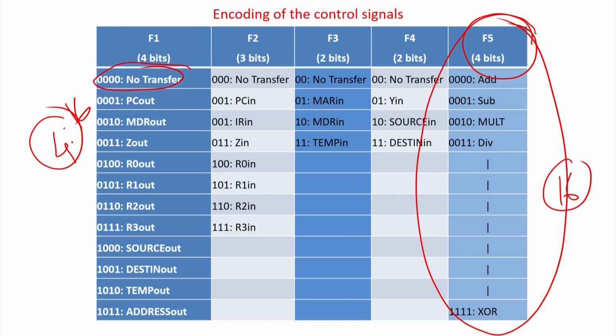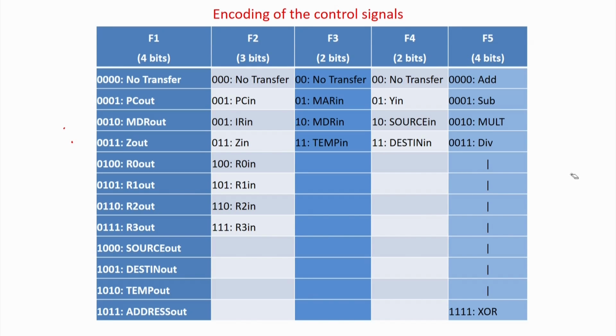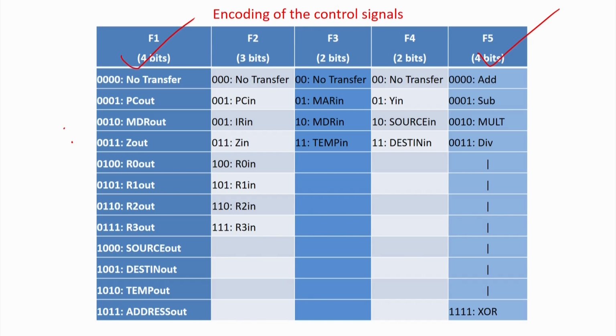If it is a multiple bus architecture, then 2 bits also can be simultaneously 1, and then again you have to break it up in the cluster. So in this discussion we are keeping this thing simple. In a single bus architecture, this is one of the very good ways of doing it. Now the read signals. Read can be multiple, because there will be only one output, but simultaneously 2 or 3 units can take the inputs together. So based on that you can make some architecture or clustering.